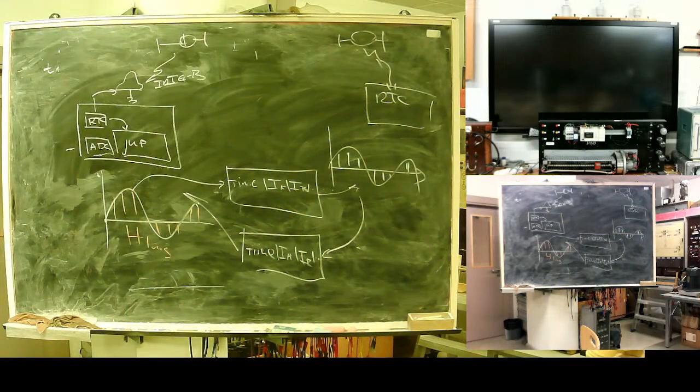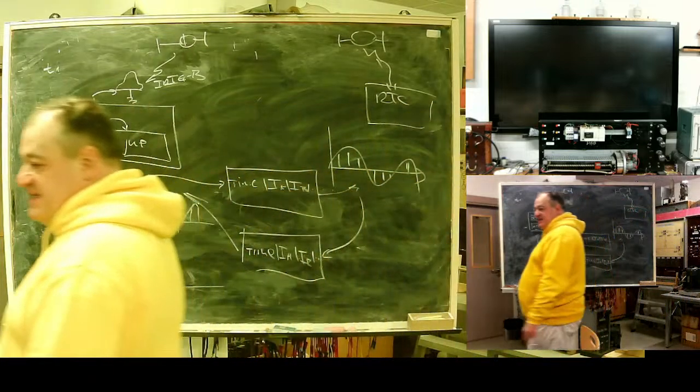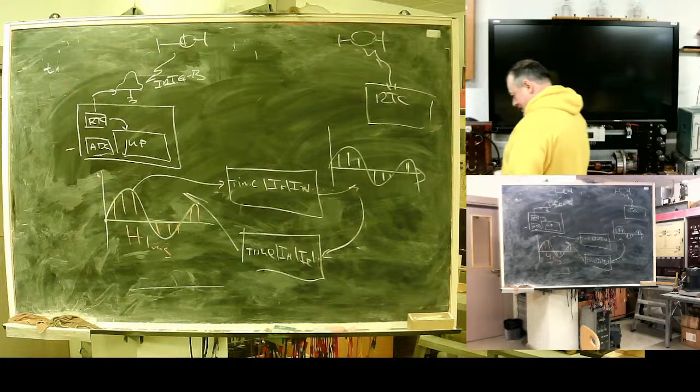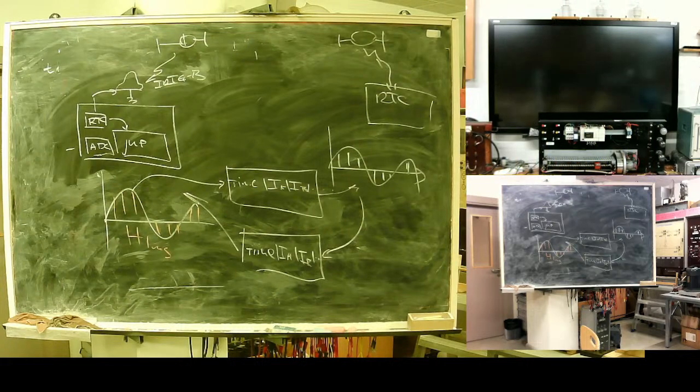All these protections are equipped with a fallback function. In case it is not possible to establish safe communication with data synchronicity, and in later versions with encryption, they fall back to distance protection.